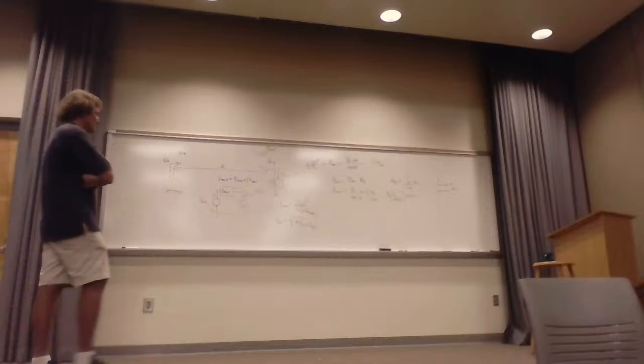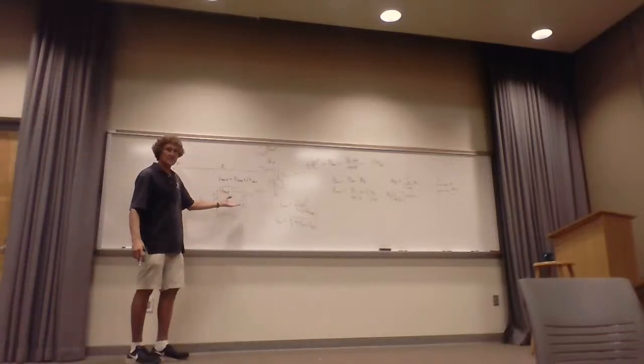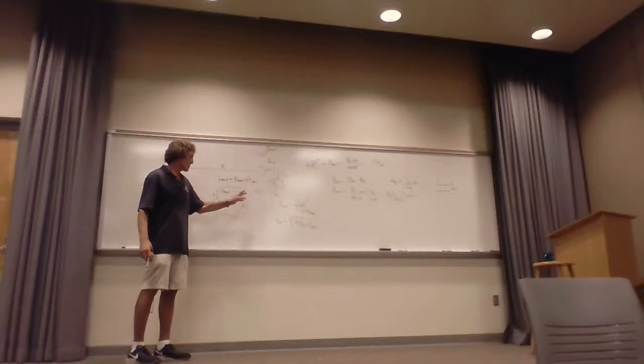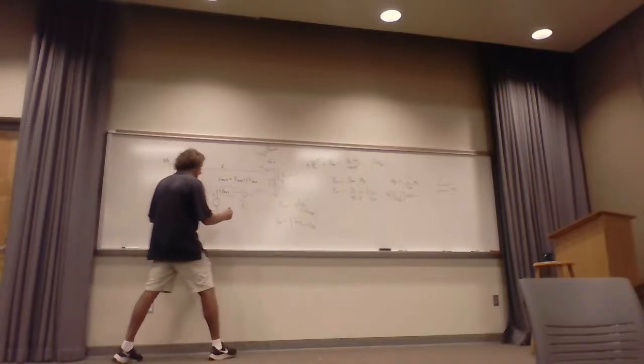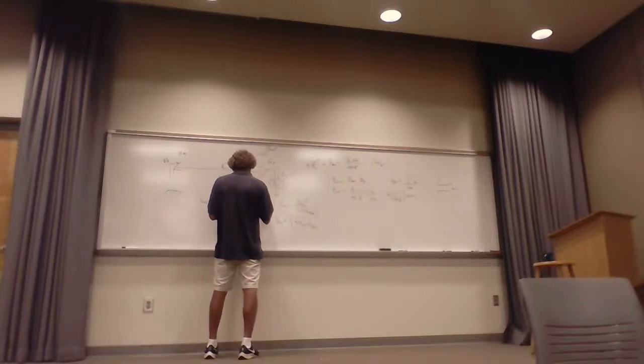Real power. You see, if that's ZL, it could have a real and imaginary part, right? If it's just an inductor, say it's got j10 ohms, no real average power is being dissipated. So to get real average power, I here would be VOC divided by Z antenna, whatever it is, plus ZL. Correct, guys?